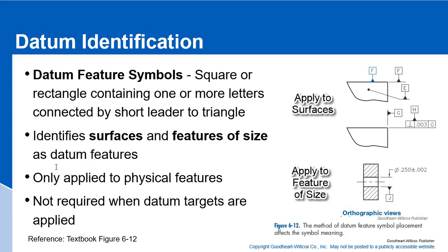Now, datums can be either surfaces or they can be features of size. Up here we're talking about how to apply to surfaces. We come off with an extension, and then we apply the datum to that extension line.